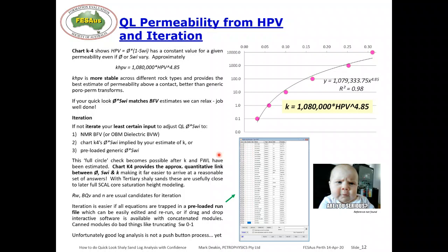It's not very difficult. If you want to change some equation for M, say if M doesn't vary as a function of Vshale like this, you can just change it from 0.325 to 0.326 in your own batch file, and then it'll work, maybe. So if you're into petrophysics, I suggest you write your own batch file and have it available to edit quickly and easily, as you can in Interactive Petrophysics, or in most software packages.